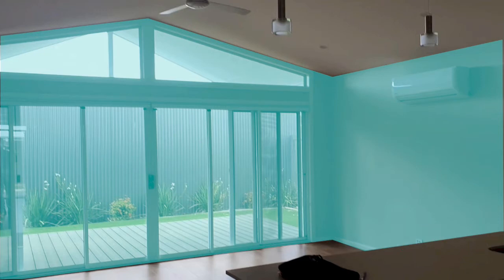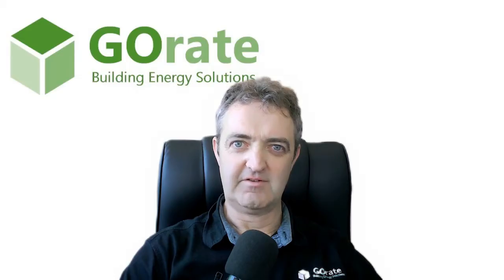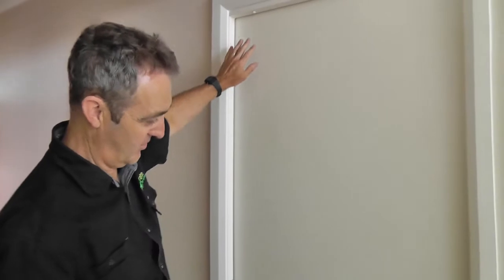Now tip the house upside down and that water is going to leak through ceiling penetrations in places like where the sweep fan is, air conditioning grills and light fittings. So basically, if you think it's going to leak water, it's most certainly going to leak air. One of the main culprits with air leakage is a cavity sliding door.